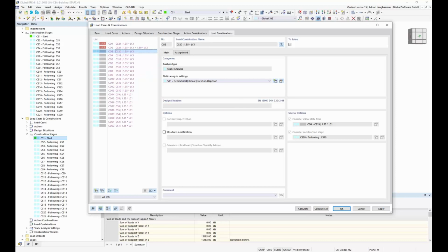And then the program needs to generate also some auxiliary combinations where it's possible to consider the load case with the used factor for the combinations. The normal stages calculation would be performed with 1.0 permanent load, and here for the combinations the construction stages need to be calculated again with the factor 1.05.